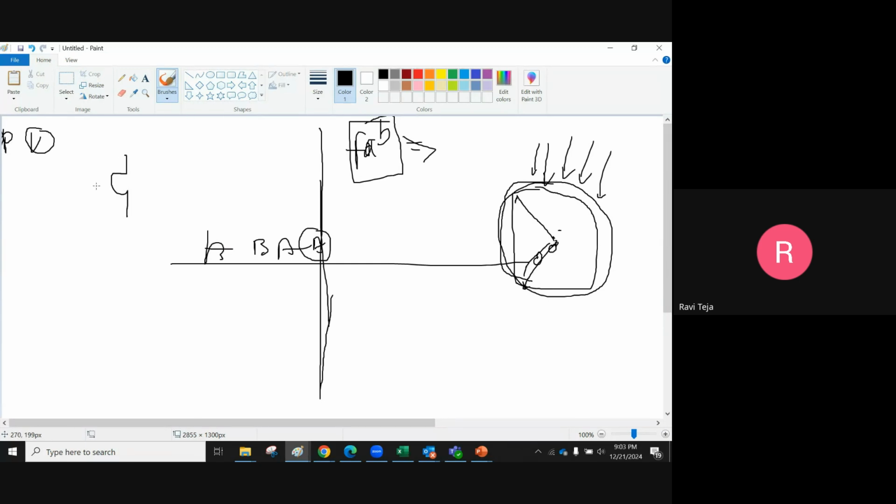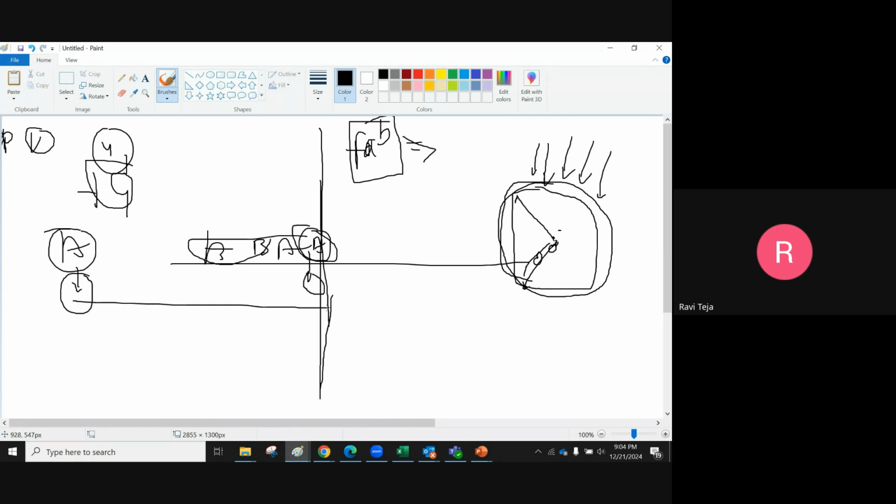If I have four common centroid devices, four A's here, and I place one A here and another A somewhere else, with some devices in between, then here the ion implantation is different and here it is different. The gradient throughout this wafer is not the same.